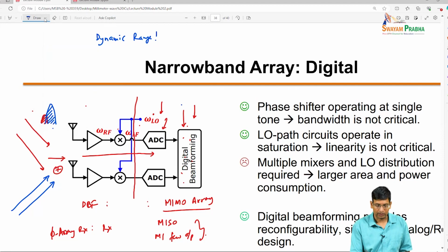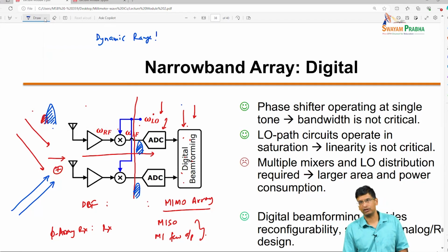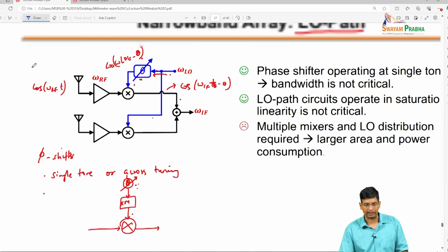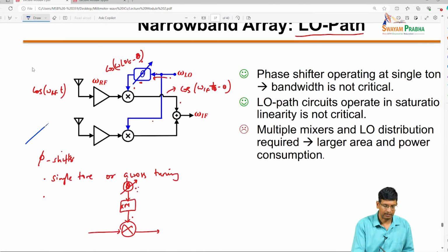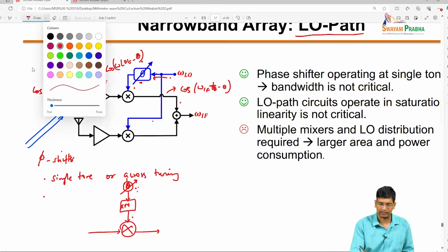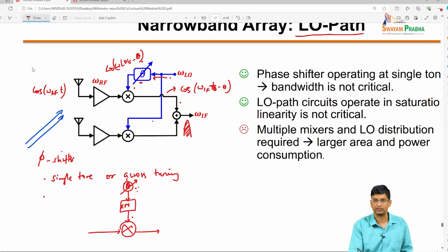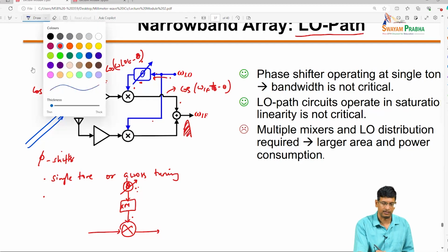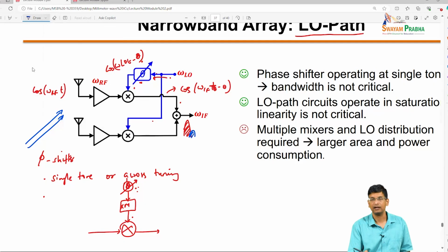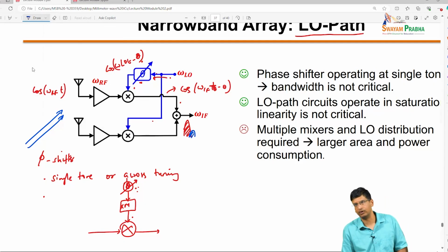Right? What is going to happen is that my undesired signal is going to be there on every ADC. There is no spatial filtering that has occurred, right? So my ADC dynamic range is quite high. Whereas over here, if that undesirable signal is coming in and I have formed a null, then what has effectively happened because of array combining is that my desired signal has gotten stronger and my undesired signal has gotten weaker, right? So my subsequent ADC can be lower dynamic range.